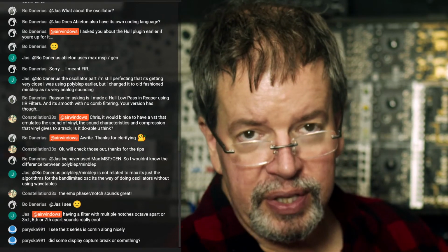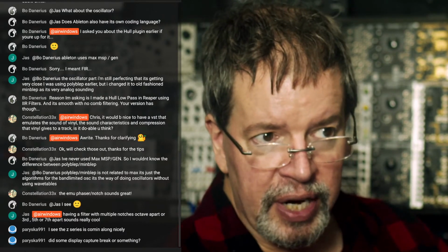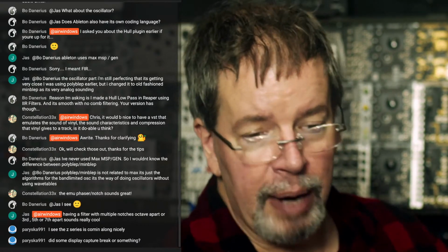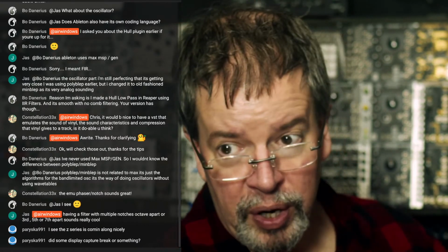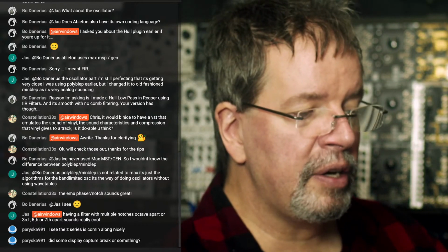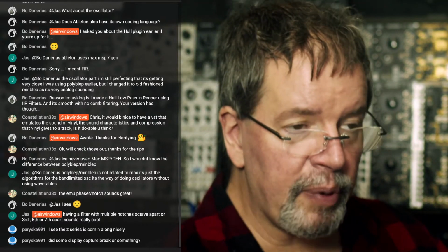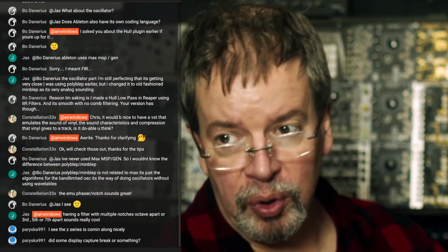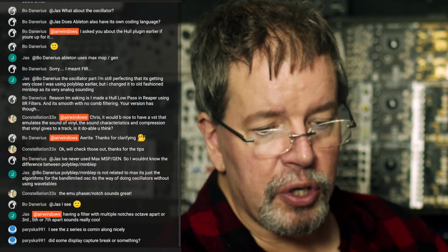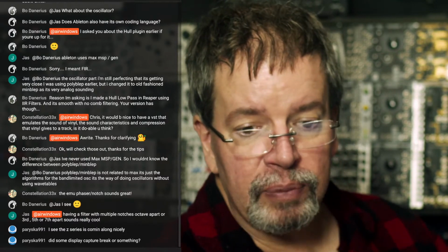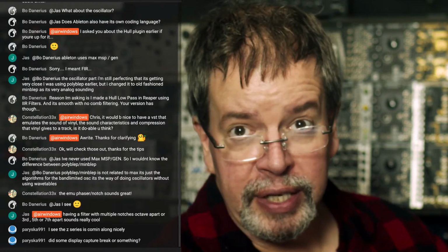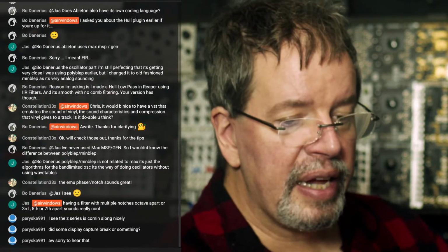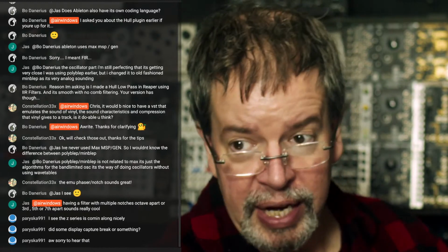So the reason that happened is because I had run this ATEM Mini a lot in hot environments or on top of another piece of hardware that heated up. And more than any of that, I had been running it with multiple things patched into it, all of which required rescaling. So the main camera was a high-resolution camera, so it already was going to have to scale down to 1080p. And then I was running the laptop, which you can't see right now.